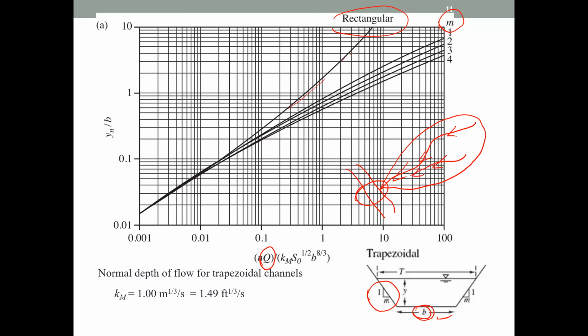What is the direct runoff? What is the base flow? So you add them together to find out this design flow rate. Probably you remember learning about an equation like the rational equation that is equal to CIA. Peak flow is equal to CIA, right? So you find out what is this peak flow. That is the one that we bring here, peak flow, right?